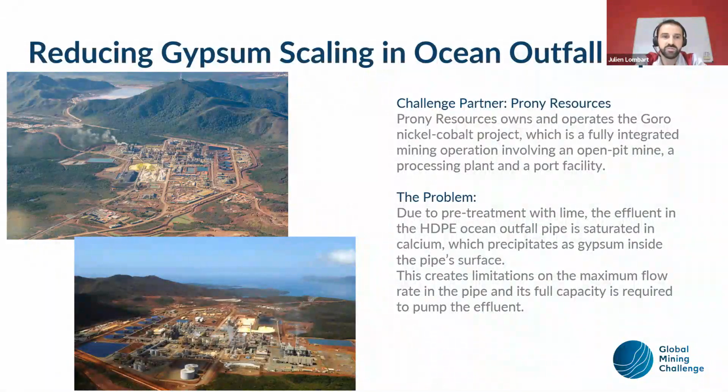We have extreme conditions in our HPAL process. We are at 260 degrees in the autoclave, so very extreme conditions. We will do the leaching, adding sulfuric acid in the autoclave to dissolve the nickel and cobalt and all the other impurities. After that, we have a step of separation of the liquid and the solid residue of the autoclave.